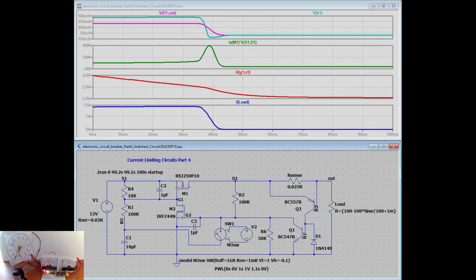I finished Part 4 with a circuit where the MOSFET voltage drop from drain to source was not part of the current limit design, which could raise the need for a heatsink device. This went against the second objective, avoid the use of heatsink devices. Depending on the transistor package, there is a limit of how much power the transistor case can dissipate without the need for a heatsink device.